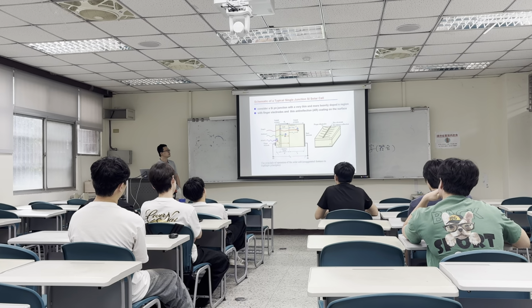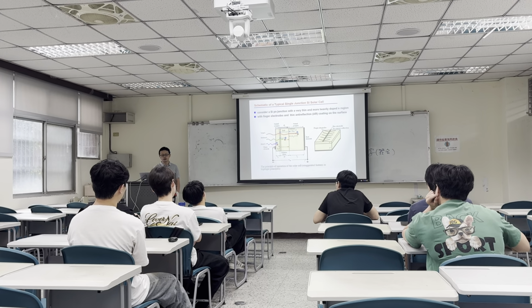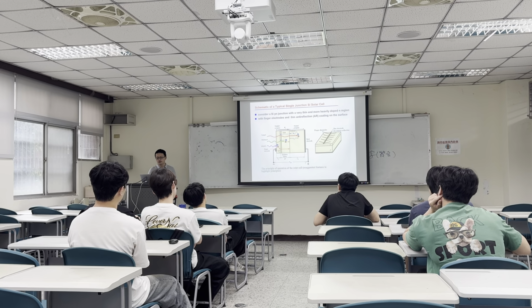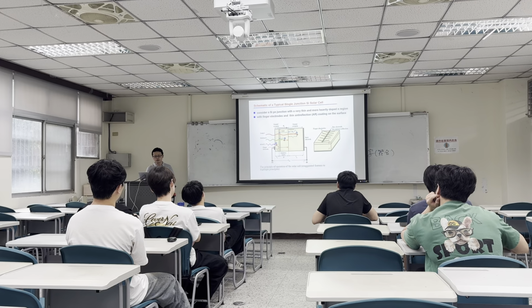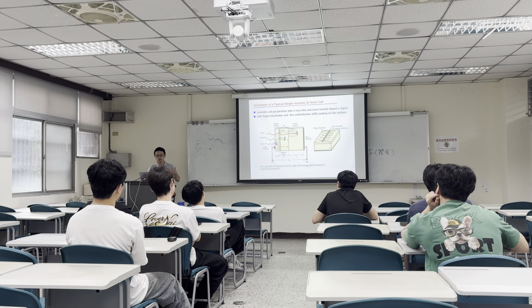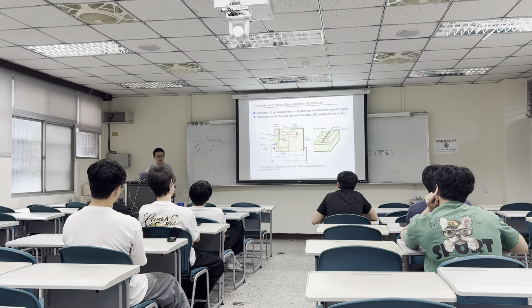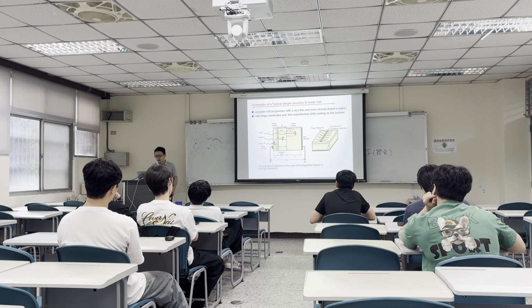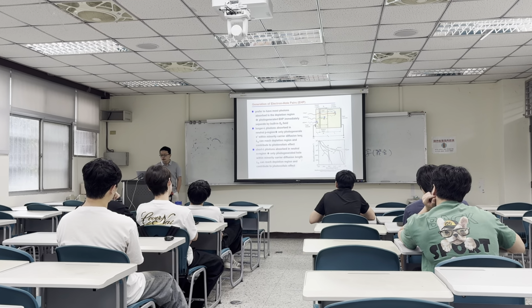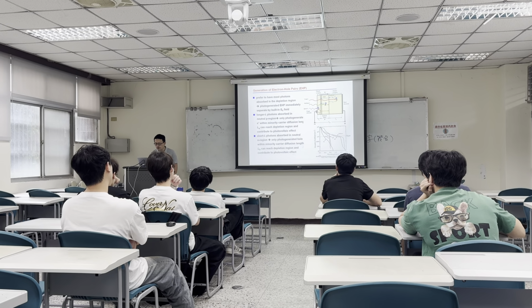Is the diagram right or wrong? This diagram to the right is our observation. The thickness for the N region is about 200 nanometers, and at the bottom it is about 200 micrometers, so the ratio should be 1 to 1,000. So in the real structure, the P region should be very thick. Okay? The P region is very thick.